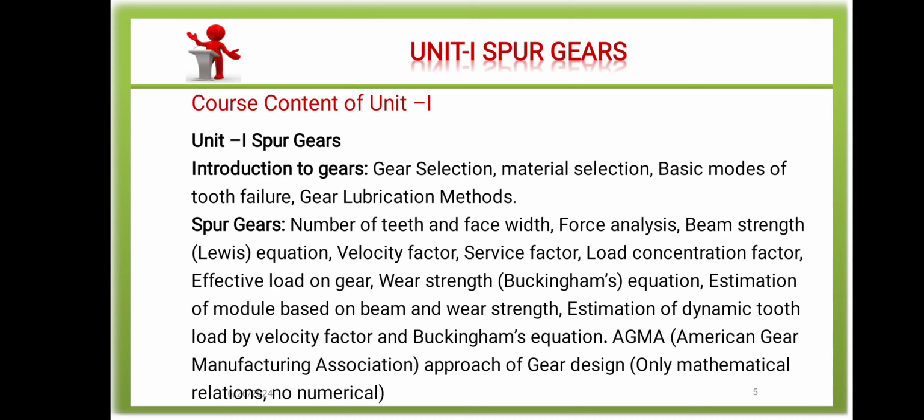So after these theory points, we will be discussing the analytical terms, that is number of teeth and the face width, then force analysis, beam strength, which is the Lewis equation, velocity factor, service factor, load concentration factor, effective load on the gear, then wear strength, Buckingham's equation, estimation of the module based on the beam and wear strength, then estimation of the dynamic tooth load by velocity factor and Buckingham's equation, then AGMA, that is American Gear Manufacturing Association approach for the gear design.